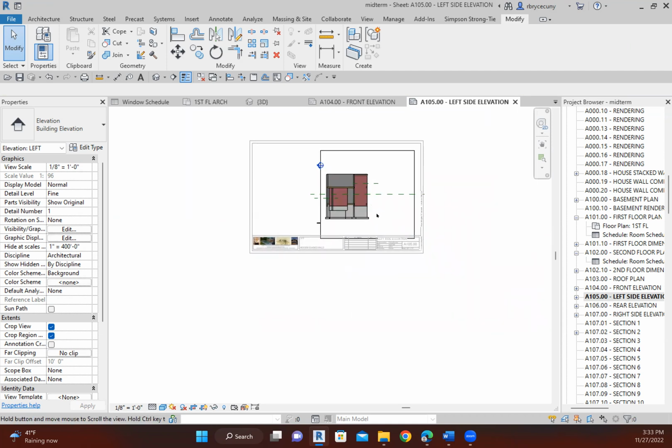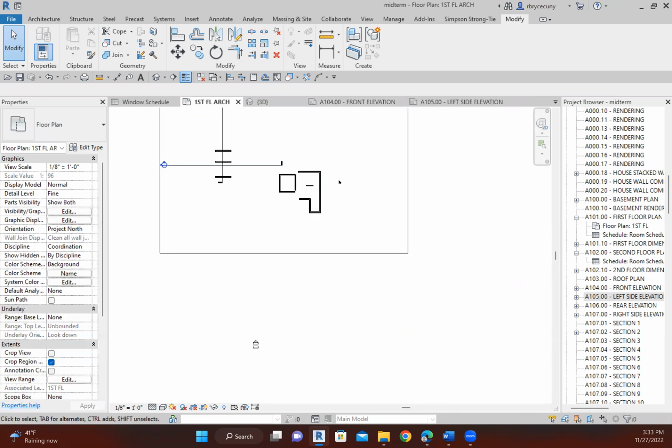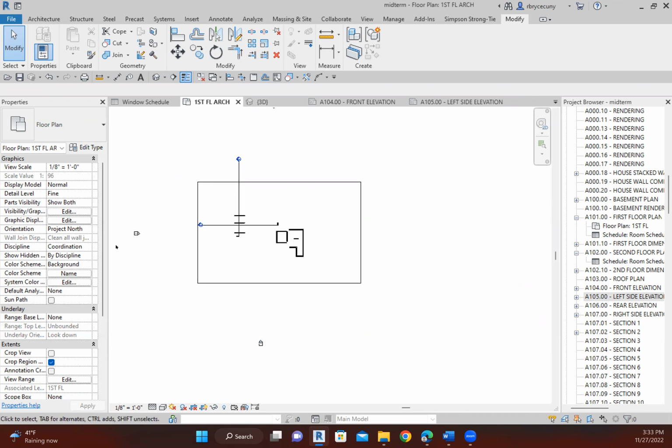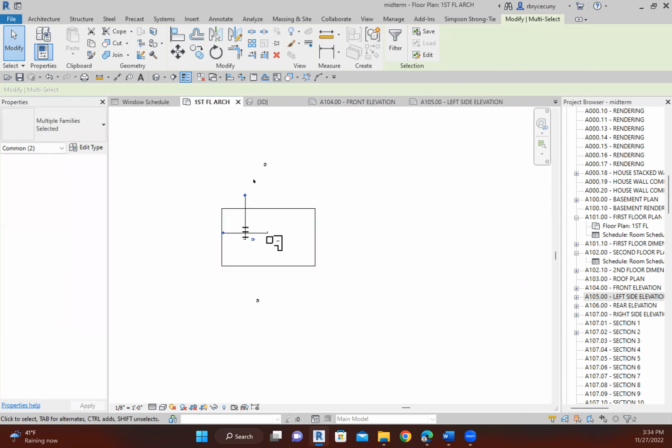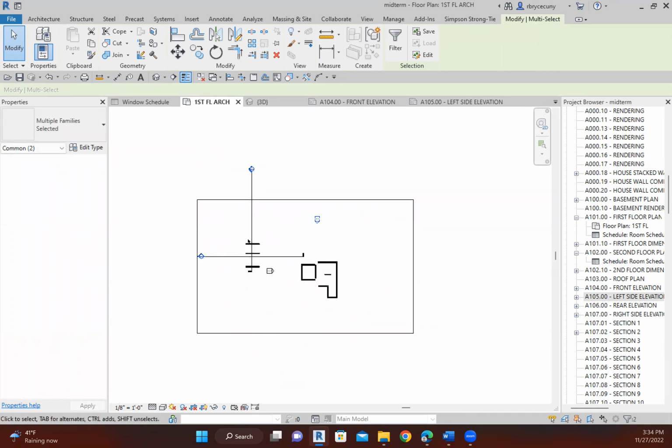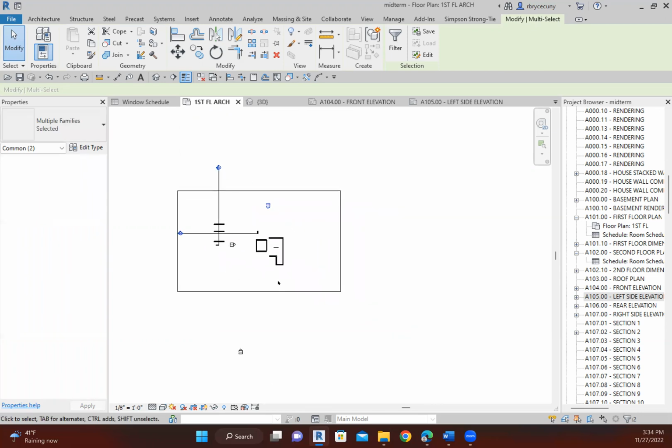And we're good to get started here on another elevation there. We do the same thing all the way around and you're ready to go. I'll give you the layout of the house, floor plans, elevation sections. And all you need to do is manipulate the floor plan so that it satisfies that criteria. Your elevations are already set. Now, if I didn't want to clean that up, I might bring my elevations a little bit closer. I don't want to see my stacked walls in my elevations.